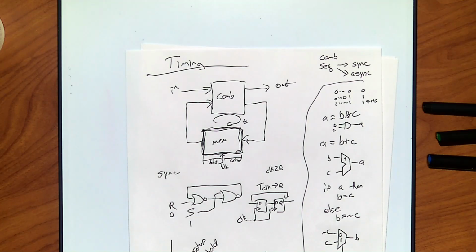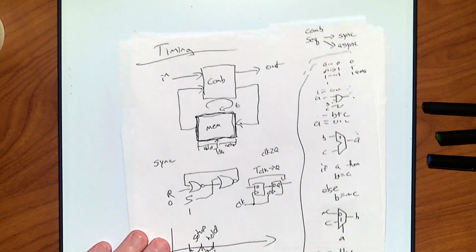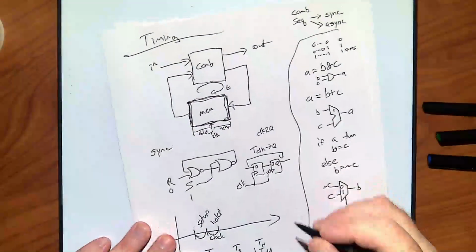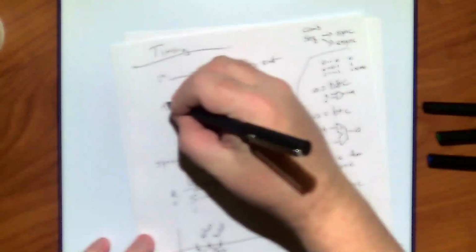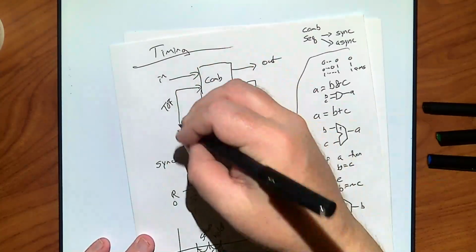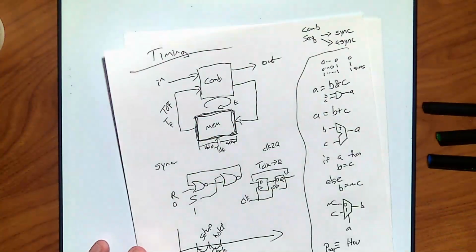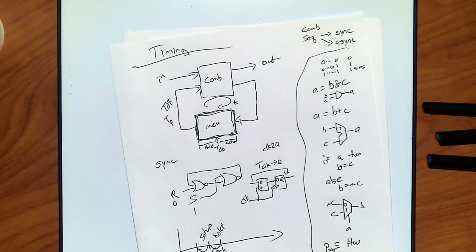So we call this the time of flight. Like an aerial flight. In our case, it's the signal going down the wire. So you will see time of flight, sometimes abbreviated as TOF. You'll also see TF for time flight. This is just how long it takes to propagate through the network. The best it could ever be is light speed, which would depend on the length.